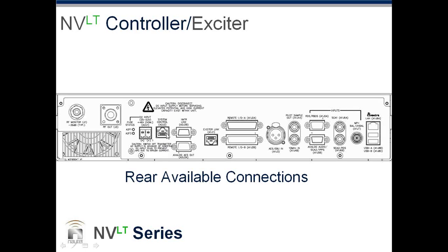The exciter connects to the rest of the transmitter control system via an Ethernet connector. Actually, the DB9 is for a lot of the comms and the control of the transmitter. Right. This is the AUI input then, or actually, for system control, is when I want to run in a larger combined system. Okay. Yep. All right. The one that you're referring to is the next one over called Exciter Link. Yep. And that is an RJ45, but it's not Ethernet. Okay. It's connections between the backup exciter. Yep. And the main exciter.